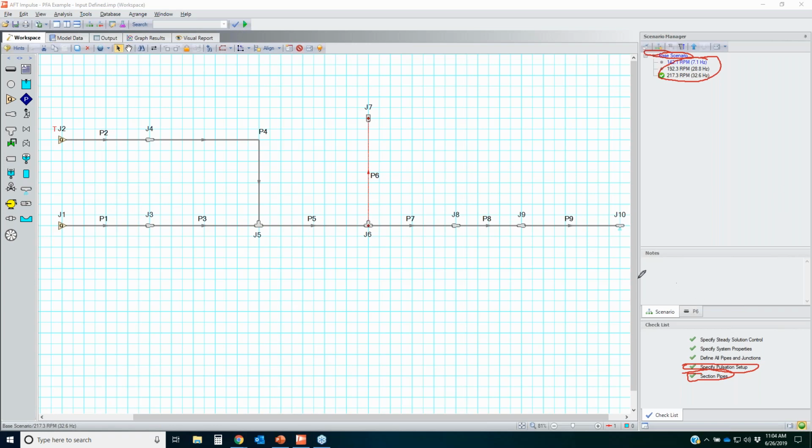Well, before I end, the next thing that you would do after that is start implementing measures on how to mitigate that. An excellent way to do that is by using some pulsation dampeners. You can model that with gas accumulators, maybe a surge tank. There are excellent companies out there that build pulsation dampeners that can help you mitigate those surges and pulsations in your system, like Blaco. Giving a shout out to Amy of Blaco, and they will do a fantastic job at helping you figure out what type of pulsation dampener you'll need once you have all these frequencies in place.